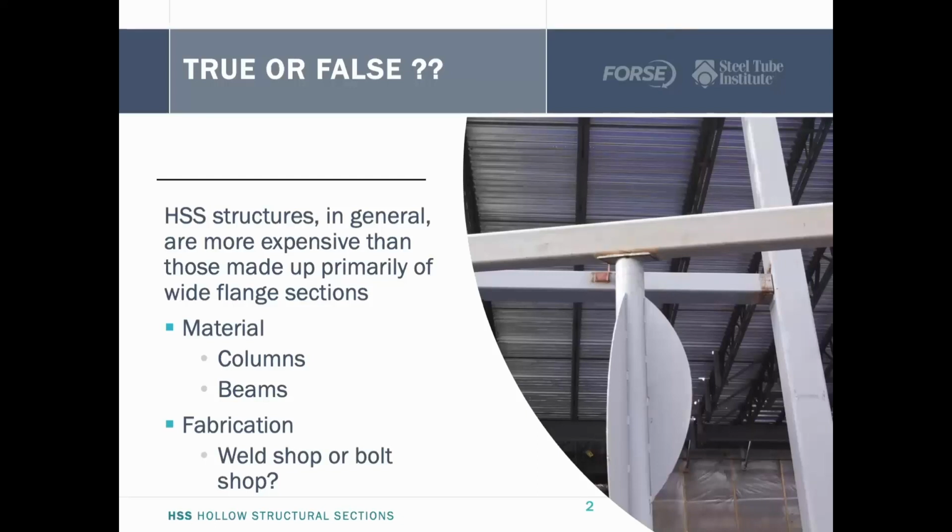Likewise, if they don't have a lot of experience with HSS, they may price the job that has a lot of HSS a little bit higher than someone that is familiar with HSS and knows how to work with it. So the fabrication component is really what I want to talk a lot about today when it comes to these connections, because there definitely are some better ways of specifying connections when it comes to HSS so that we can try and keep that total cost of the material and the fabrication down.